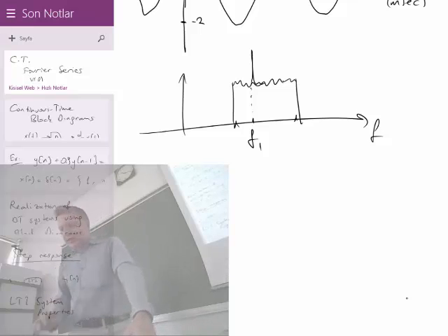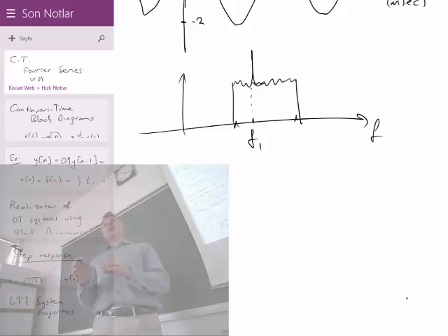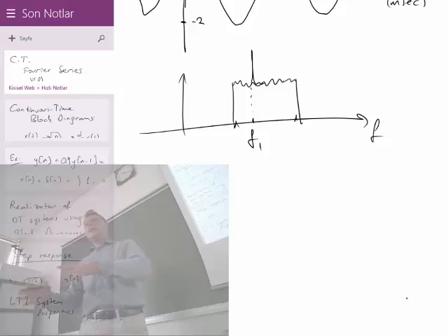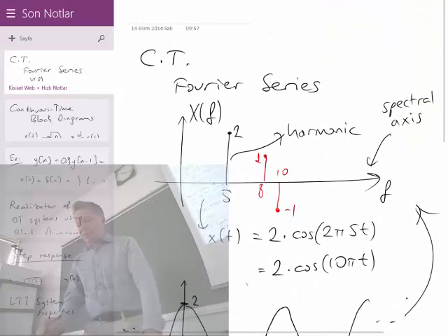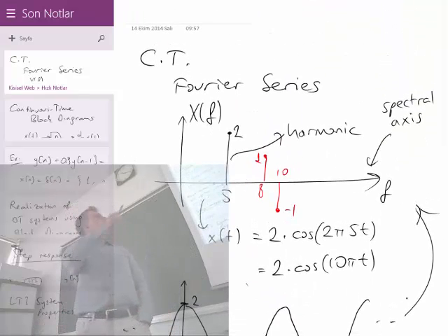So today we will start with the first strategy to transform signals, periodic signals, and continuous time periodic signals onto the frequency axis. We will learn how to do that. And that is called the continuous time Fourier series. This term series, not the transform, but the series, comes from the fact that the input signal is periodic.